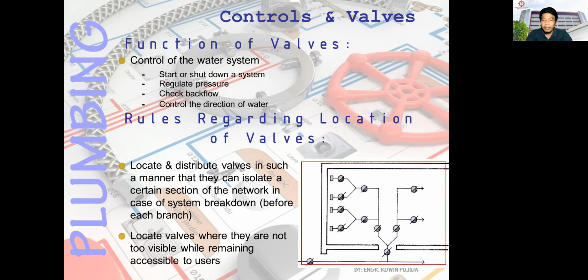Okay, so this is the diagram. Before you branch out, you should have a valve here, and then if you need another branch, you have to put another valve. Sometimes this is a gate valve.